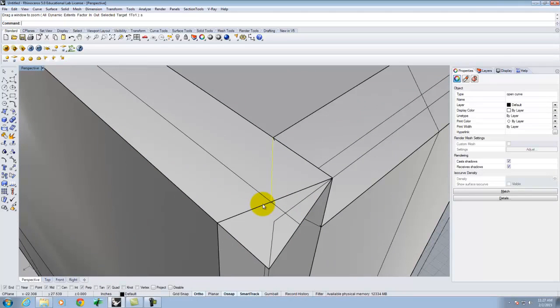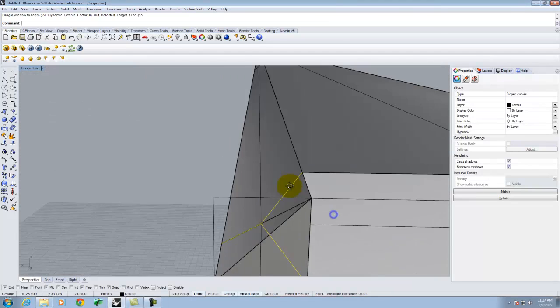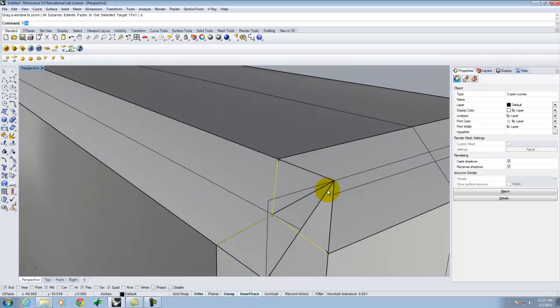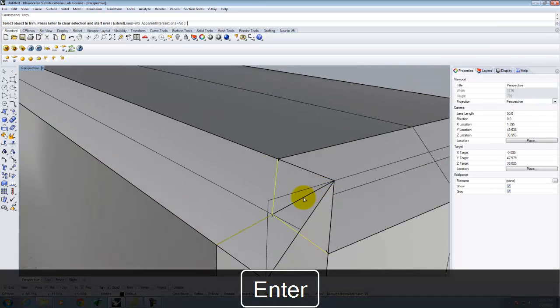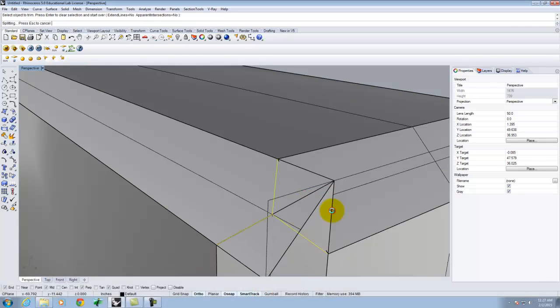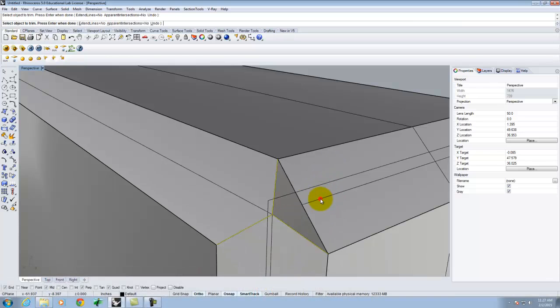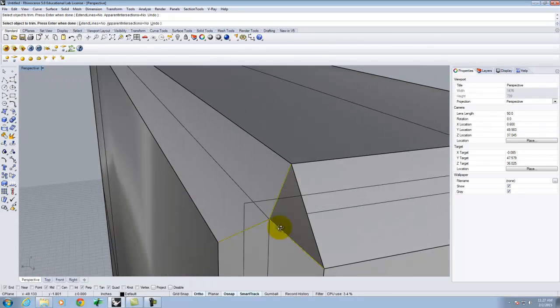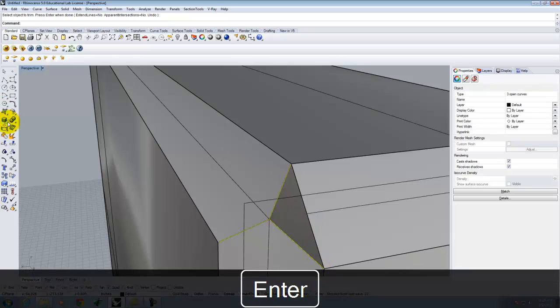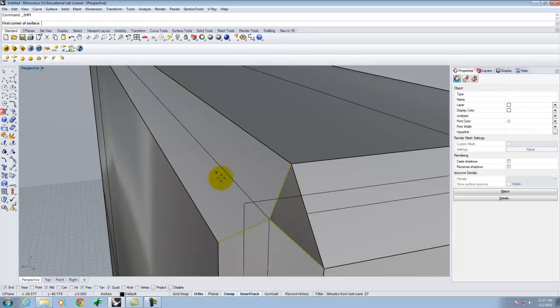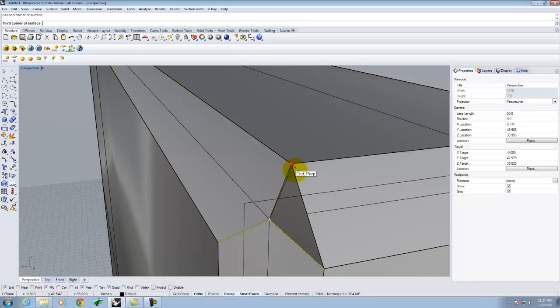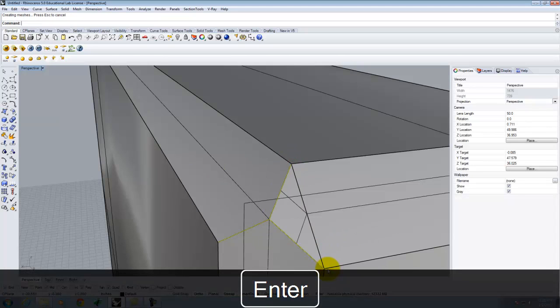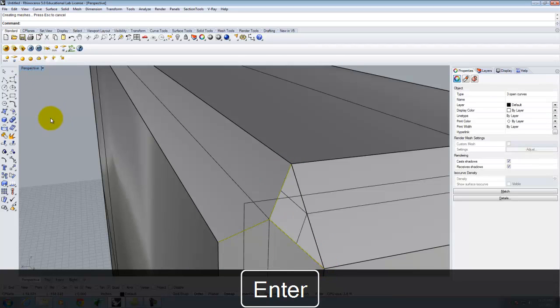Okay. Now let me take that star instead of a triangle there, and I'm going to use those to make my trim. So I'll type trim, or go to edit trim, and we'll go ahead and start to trim off these surfaces. Trim it that way. Alright, pretty good. Now in this instance I have a little piece that was missing. That's fine. I'll go back and fill that one piece in with my surface from 3 or 4 corner points. There, there, and there. And I end up with the opposite of what I did last time.